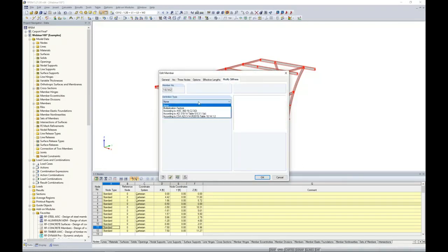Well, this allows us to modify the stiffness according to the AISC 360. Now, again, the ADM 2015 lines up exactly with the requirements from the AISC. We will determine what that tau sub b factor is, and we will also apply a 0.8 factor to the flexural and axial stiffness. So now this will be applied to all members that contribute to the lateral stability. It is also a conservative approach just to apply this to all members as well, including gravity members.